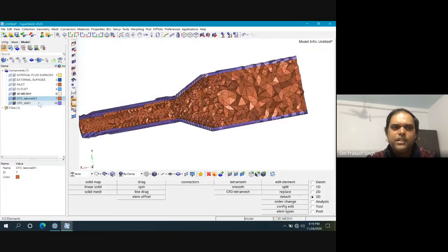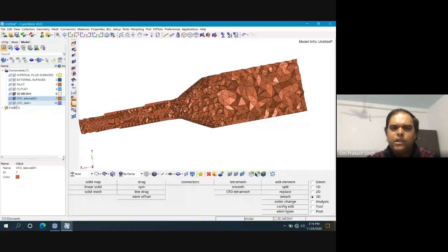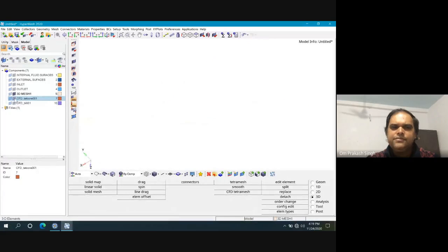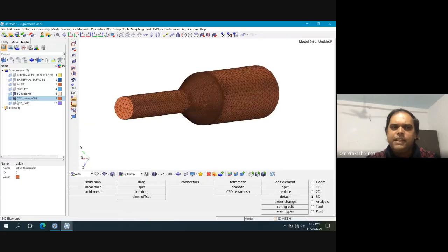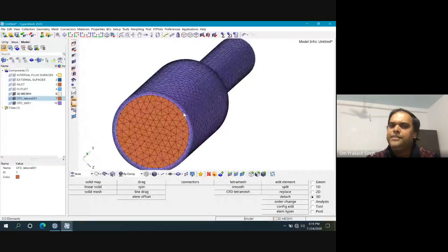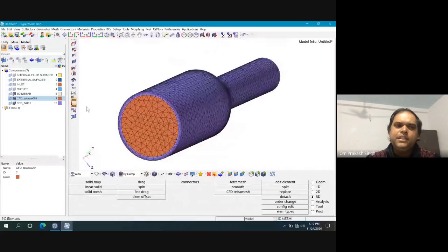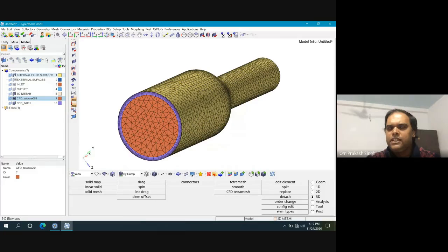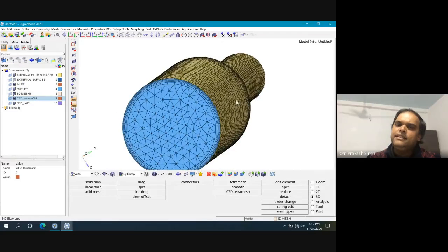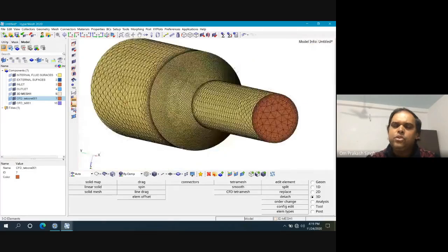Okay, and the rest, look, this is the core of our mesh, the core of the 3D mesh. Around it we also create a boundary layer mesh. Look at the boundary layer, this is the core of the boundary layer. And above this, of course, the three are the inlet, outlet, and the closing volume walls. If you take this inlet, outlet, and this mesh, then this is what goes into Fluent. Yes, does anyone have any question?